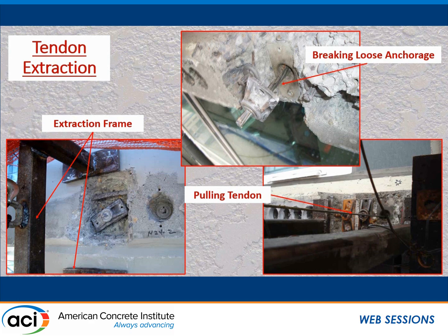And again, one of the things I mentioned earlier was, as soon as you can extract that cable, you can see where the break is. You can then hopefully find it and go in and do your excavation there and couple it possibly. Or you take the whole thing back out. Sometimes the biggest challenge, on the right there, is just breaking the anchor loose to be able to pull it out. But there's going to be a mess. There's a lot of grease. You've got this 80-foot, 120-foot long piece of greased up cable. You've got to dispose of it. If you're on the exterior of a building in a swing stage, that gets to be a little bit fun.